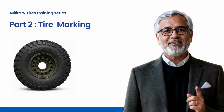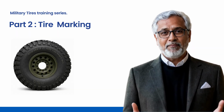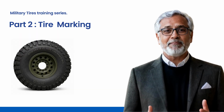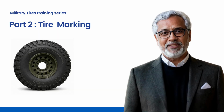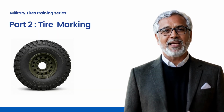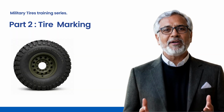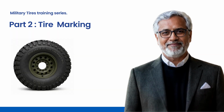For engineers, this is important because tyre markings influence load capacity, speed capability, mobility, gearing calculations, suspension design and overall safety. By the end of this session, you should be able to look at a tyre marking and understand the key engineering information it provides before selecting or integrating that tyre into a vehicle.